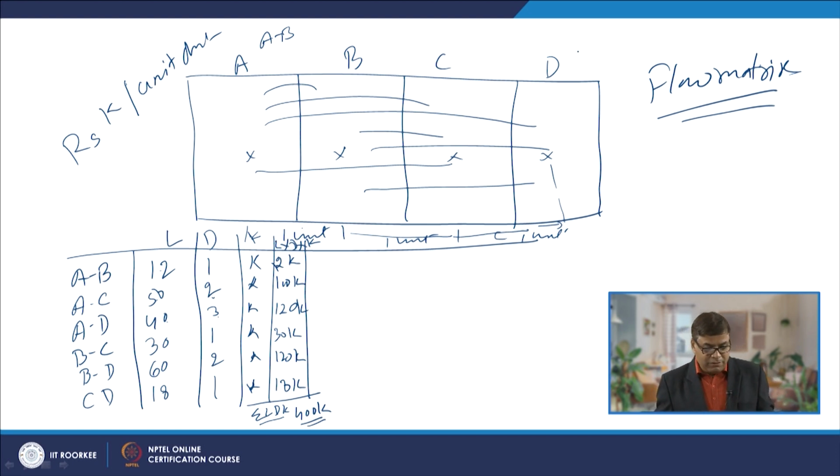So, in this setup, when the facilities are arranged A, B, C, D in sequence, the cost occurring in this layout on account of all types of movement is coming to 400 K. If this arrangement is shifted a little bit, the work centers which have high load into distance values can be brought close to each other, or those work centers which are causing higher cost can be brought close to each other.